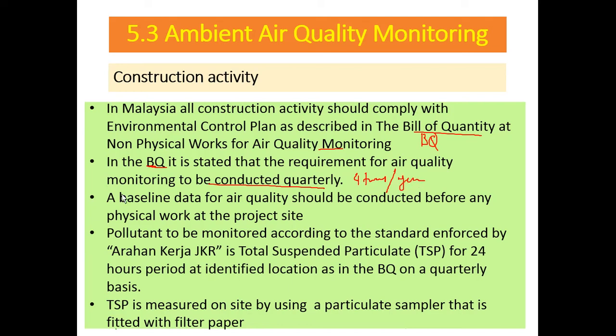Okay, so the baseline for the air quality should be conducted before any physical work at the project. Baseline is important, as the reference data. This is the limit that you need to not exceed when the construction activity starts in that area.